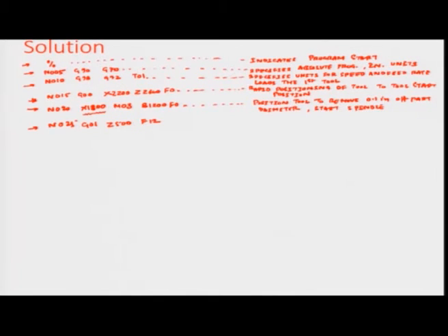The units are basically inches per minute, as has been defined earlier for the feed and speed rates in line 3 of this particular program. And so, you can say that this corresponds to the feed tool into the workpiece for the first case, that is the 0.1 inches depth case.